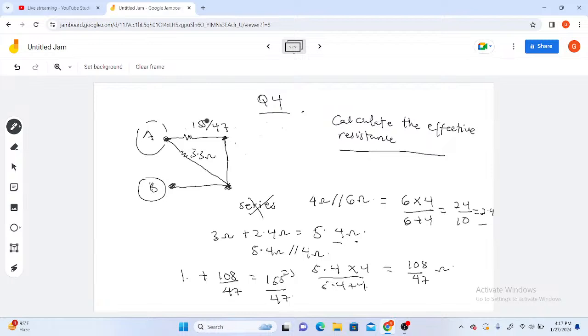So now at this point, what do you see? Our circuit has now been simplified to only two resistors available here. How do we simplify these two resistors? Once again, we need to see that they are either in series or parallel. So how do we notice that? Is there a node? Yes, because please take note, the terminal A here has a node here, and there is a terminal B here. So A will split. Let me clean this portion so you see it well.